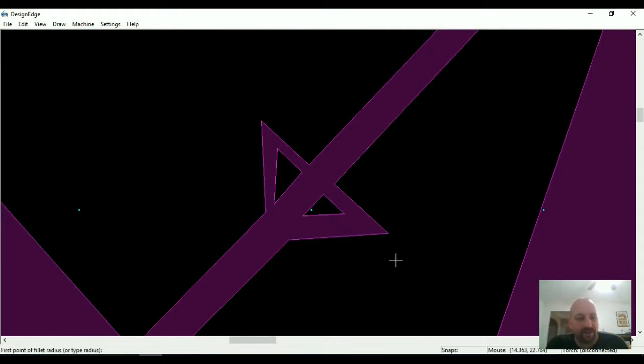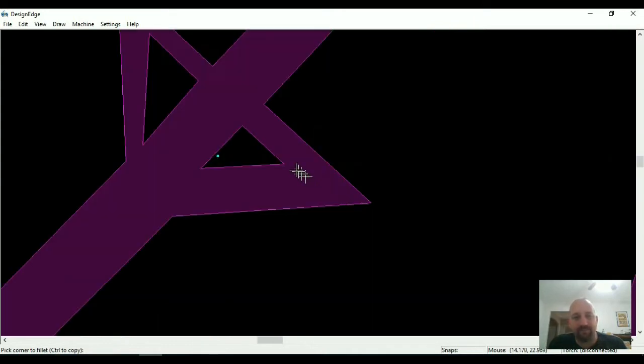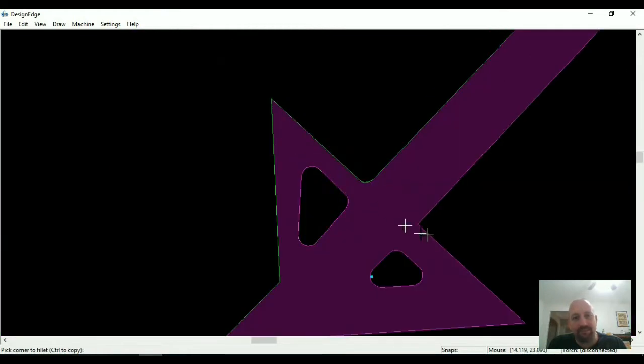And so if I do a fillet, not a fillet, that's for catfish, but if I fillet with just around a sharp point, so if I fillet at 0.045, that is my kerf, but that's the diameter, so I need half of that for the radius, so I put a /2. I can do the math right there in the command line, and then I can click on these and see what will actually fit.